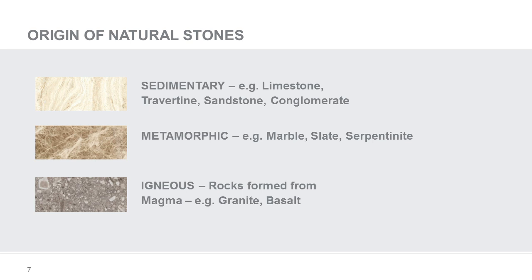Metamorphic rocks, which are modified by heat and pressure, such as marble, often have mineral veining. Some marble tiles can be weak and may have a mesh backing or resin on the reverse tile to strengthen them. Such backings need to be checked to ensure that the backing mesh and its water-resistant glue are well bonded and not flaking. Some green marbles, for example, have been known to be adversely affected by moisture since they contain clays. Seek additional technical advice when specifying these, as they will probably require special installation materials.